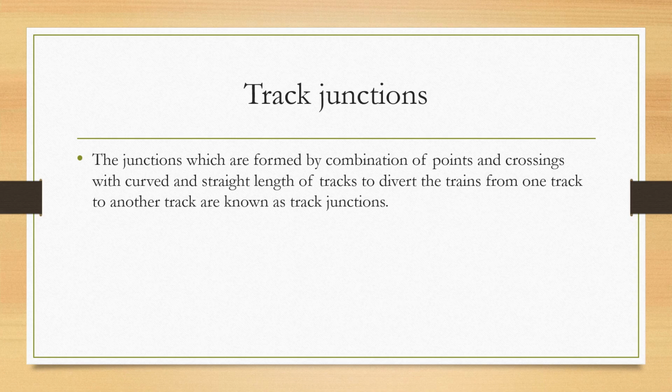Tilting of rails. It should be checked and rectified. Bolts and fittings. These should be very tight with the exception of a few heel bolts.